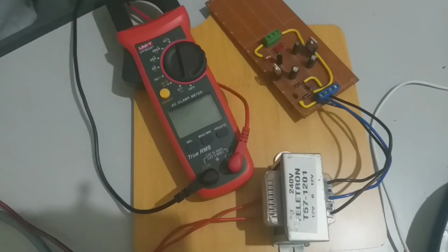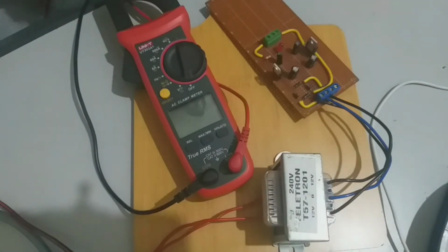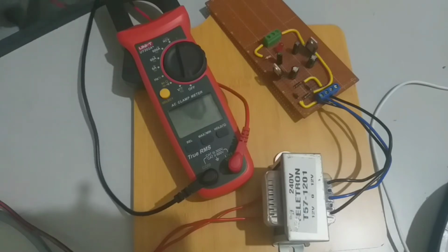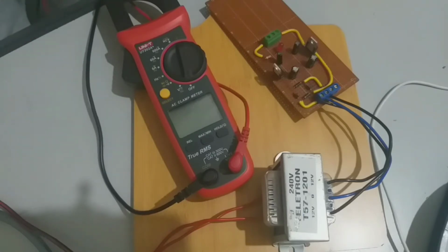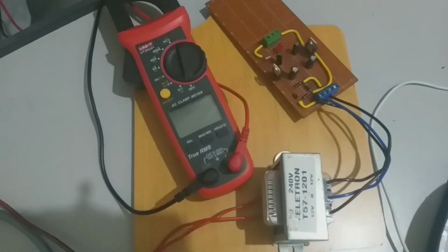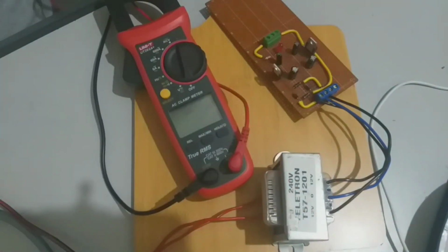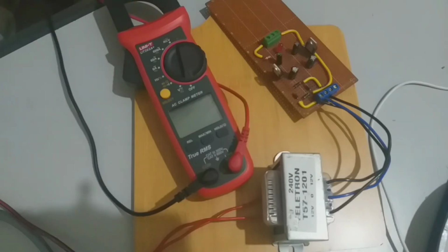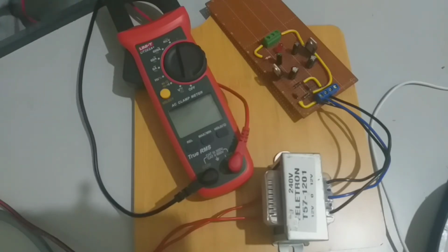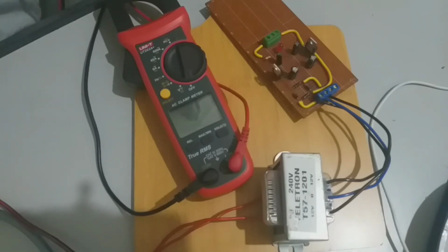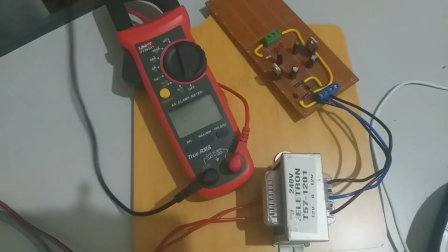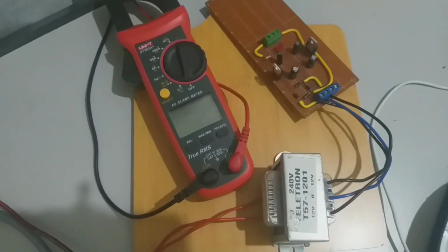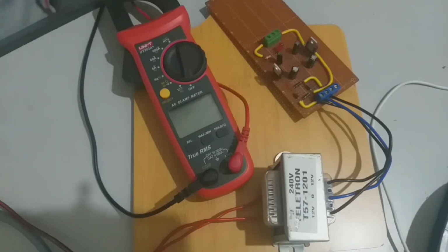Today I am going to explain the overall process involved in our circuit. One of the test conditions that must be met for LM7805 is the input voltage supply. The amount of input voltage supply given to this circuit is 12 volt. The range given in the datasheet of LM7805 is within 7.5 volt and 20 volt, whereas the input voltage supply given to LM7905 is negative 12 volt. The range given in the datasheet of LM7905 is within negative 7.5 volt and negative 20 volt.